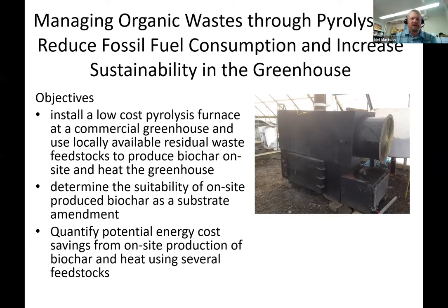What we found, which maybe shouldn't be as much of a surprise, in terms of using those wood feedstocks that we had available to us, is that it was all about quality control. In the end, we found that municipal wood chips were too variable in their size, and we needed commercial screening options to make them viable. So we weren't able to use this particular furnace with the free municipal wood chips that we had access to. Moisture control was also really important, and one would have to set up a large system on your own operation to ideally cover wood chips and avoid rain, so that they would have a low moisture content by the time they would get used in the winter time.